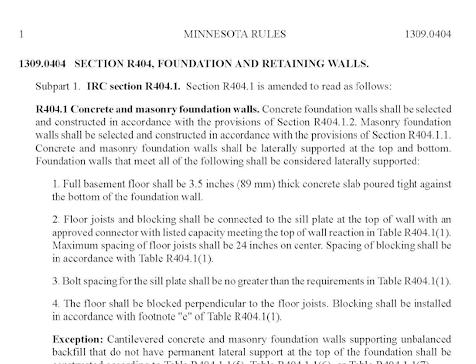In order to calculate the size requirement of the cement pads, we need to know the soil composition and compressibility. This can be done with actual soil tests, or it can be done with the geologic survey of the land on which the home will be constructed. The type of soil that was at my construction site had a compressibility of 2,000 pounds per square foot. Once again, to over-engineer, I designed my cement pads for a softer soil of only 1,500 pounds per square foot.